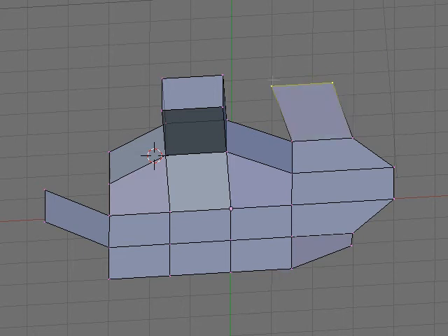Now we use movement like we did before with the object by pressing Y, and now it's set to the Y-axis, and now I can only move it along on the Y-axis. It's the same with X. This wouldn't make sense, as you can see, or Z. Now I move this face along on this edge along on the Z-axis.